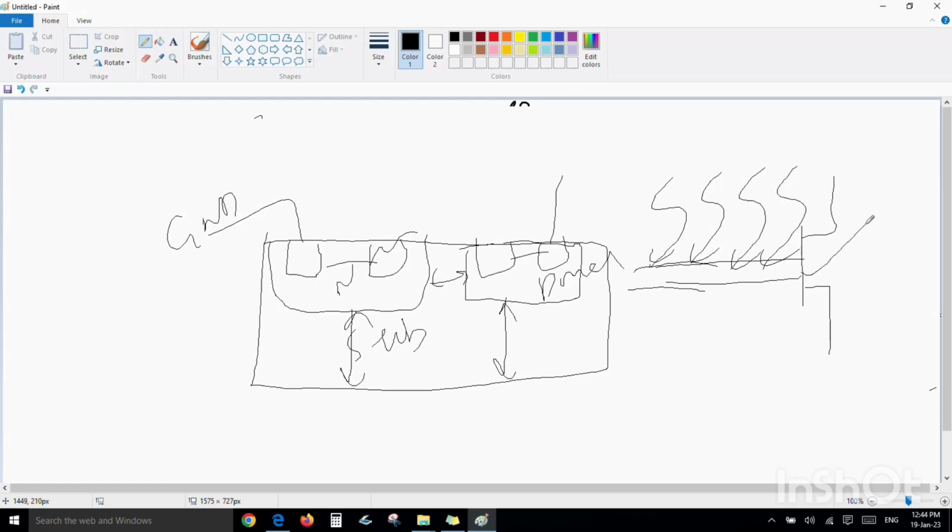So I will break my net into small pieces, like metal 1, metal 2, metal 1. We call this a jumper, and we need to place these jumpers inside my design so that it is easy to fabricate.